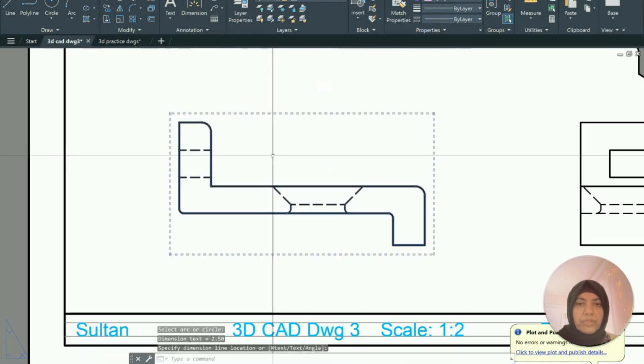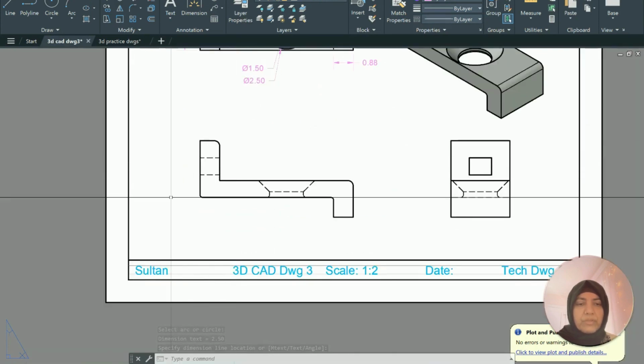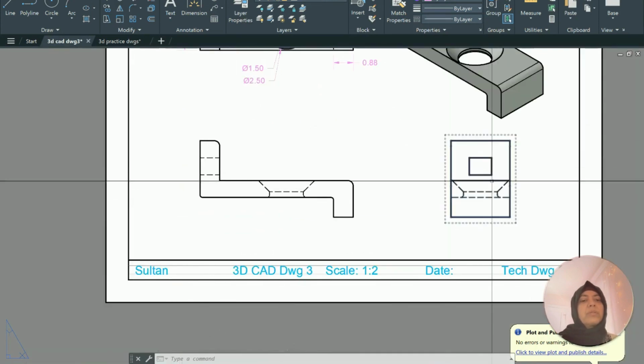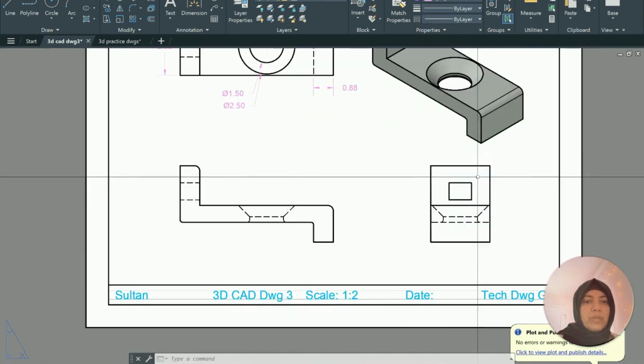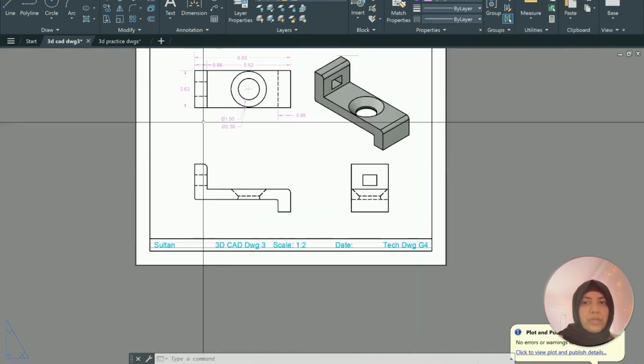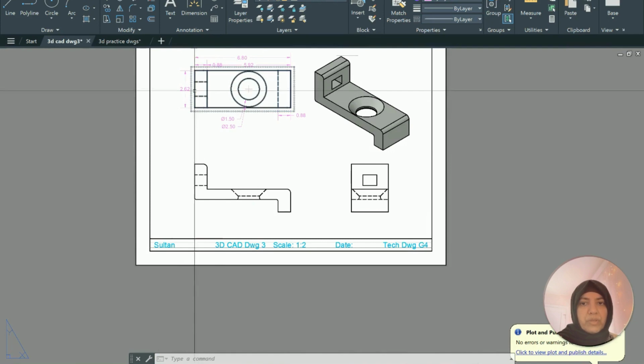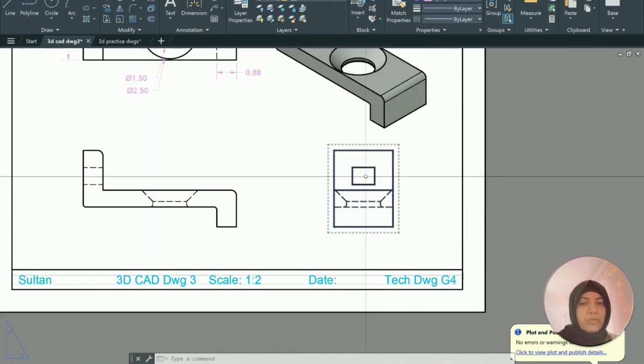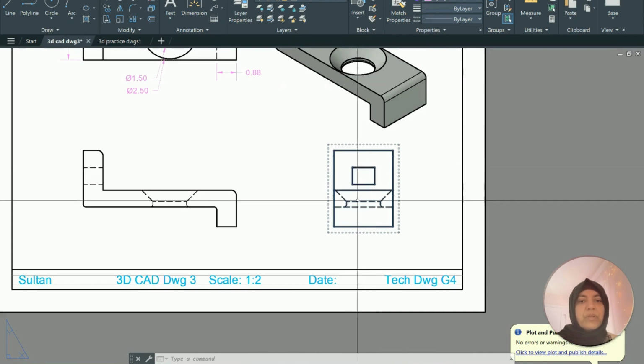Now for the elevations, you want to add the heights, and the only exception will be the element that is not visible clearly, such as this opening. It's not clear and it's in hidden, so you are going to add that width over here as well.